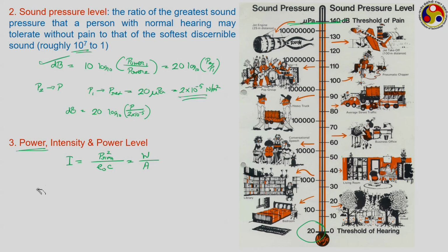So, if we go by it, then the corresponding power in terms of decibel will be equal to 10 log base 10 of W for the measured signal divided by W ref, and for this reference power, the most common choice is 10 to the power minus 12 watt, which closely resembles this particular pressure level.